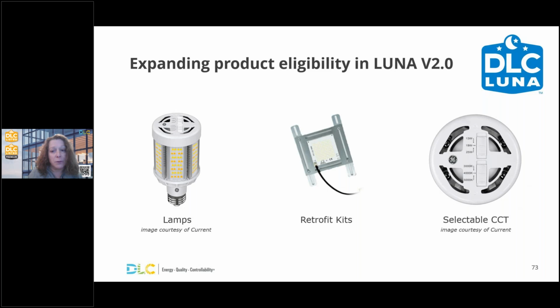And we're also proposing that field adjustable light fixtures can qualify to Luna, which is new, even if they go above 3000K, as long as they are shipped set to the lowest Luna qualifying CCT and the lowest wattage. This aligns with new SSL 6.0 field adjustable requirements, as Jason mentioned earlier, and taps into common contractor behavior. Next slide.